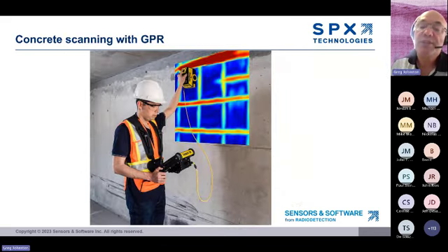The main reason that concrete scanning with GPR is popular is for avoidance. GPR images allow cutting, drilling, and coring the concrete with much less risk of hitting an embedded object. Cutting through a post-tension cable or a conduit is not good for obvious reasons. Even cutting through rebar is frowned upon by structural engineers.